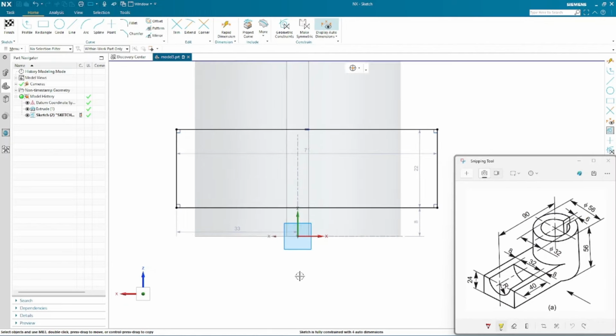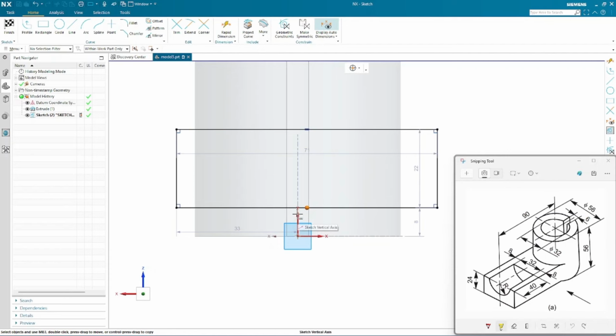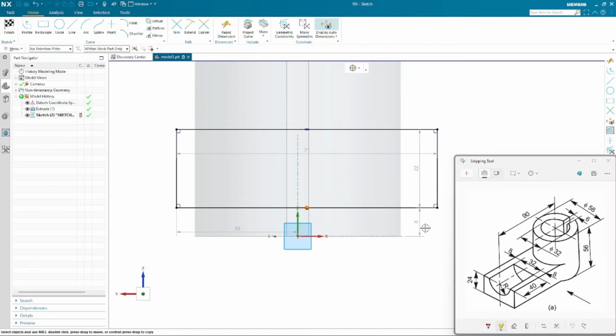In order to do that, I'll pick the center point of this line and constrain it. There are two ways I can do that. One is, as in the previous sketch, I can pick this axis and put it on curve. It will be here, but then vertically I'll have to give a separate constraint to position it on the bottom.